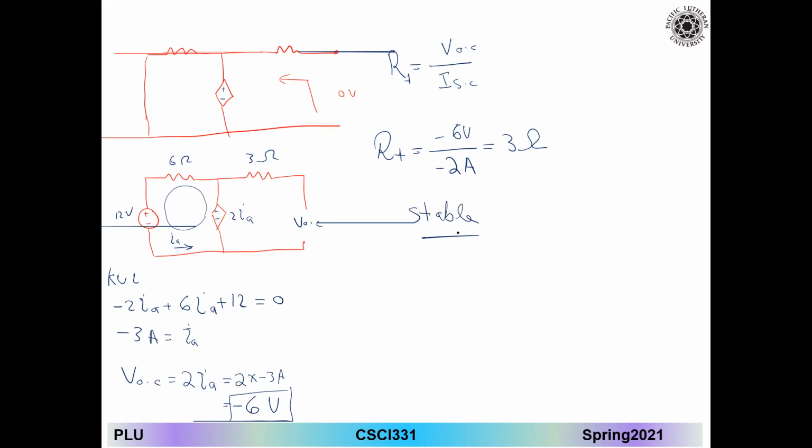So now you have a sense. Sometimes we end up with a negative R if we find R Thevenin in any way, and this value could be negative. There is no real-life negative resistance. The only indication is that your circuit is unstable.